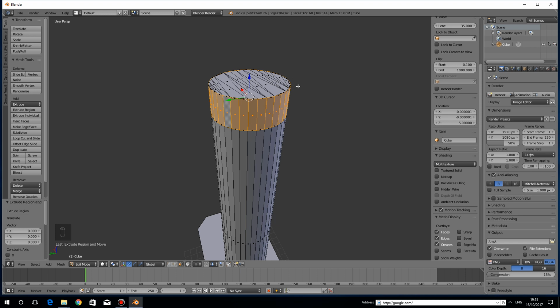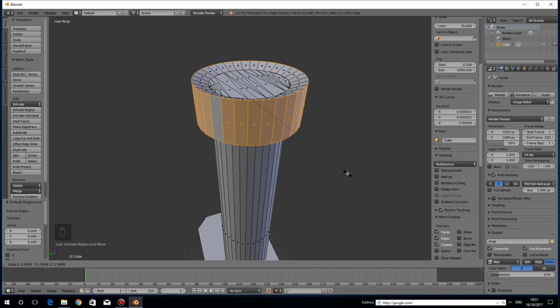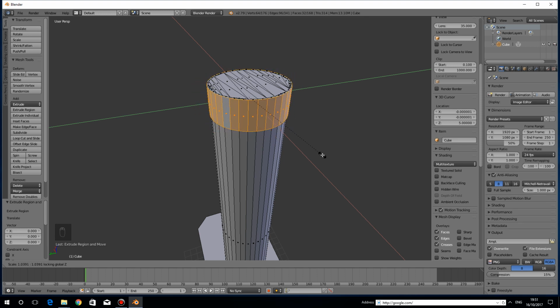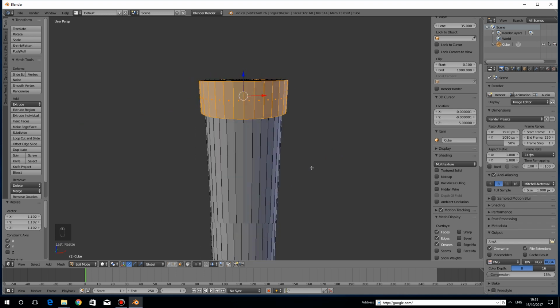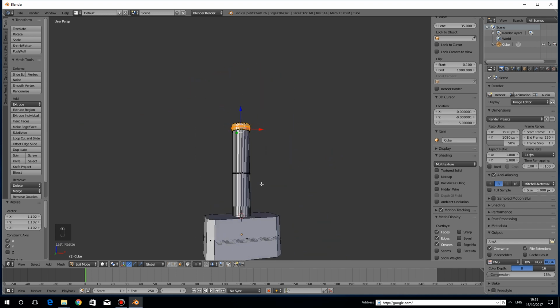We've now created extra geometry. These faces are now doubled up. So if we press the S button and scale it, as you can see, it creates the extra geometry we need. But as you can see, it's moving on all axes. We don't want it to scale on the Z-axis. So to do that, we exclude the axis by pressing Shift and Z, and that gives us a nice flat. Oops. Do that again. Extrusion, and there we go. We have the cap for the hammer.